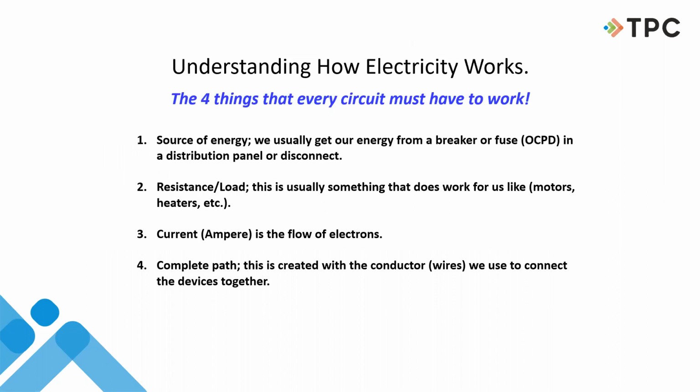And so understanding how electricity works is that source of energy. The print's going to tell us where that source comes from. And with most machines, there's going to be several sources of energy. Typically, you have a higher voltage one, which most of us probably would say was 480 in some cases, might be 240 or 208, but somewhere in there. And that's usually for our motor loads and those kind of things. And then we have transformers also in that panel sometimes, and that's usually for our control voltage. Could be DC or could be AC. That's going to be on the print.